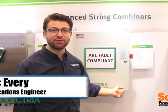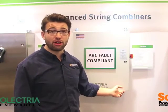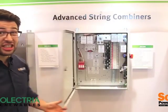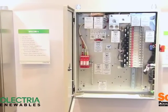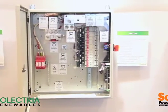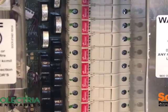I'm with Selectri Renewables. I'm an application engineer here, and we're here at Intersolar to talk to you about our Arcom, arc fault enabled string combiner. It's listed to 1699B and is available on the market today. It's available in 8, 12, 16, and 24 positions. Comes with touch-safe fuse holders and string-level arc fault detection.